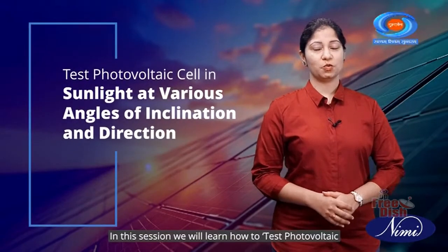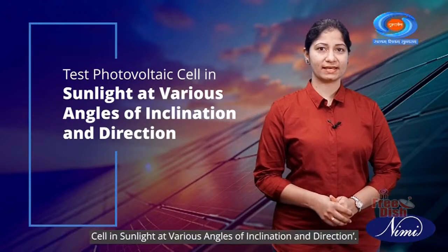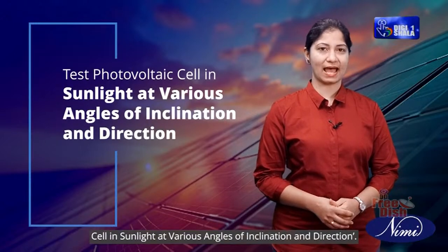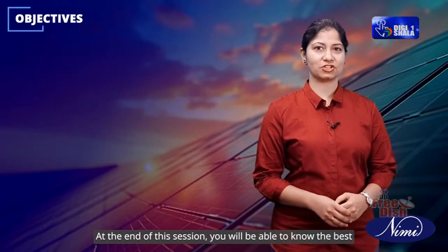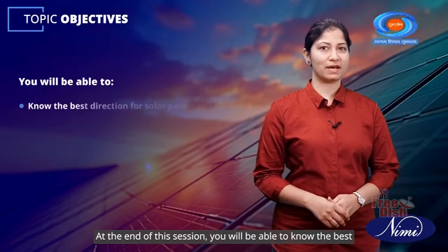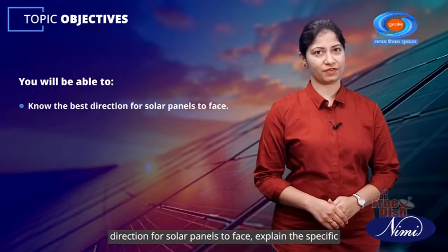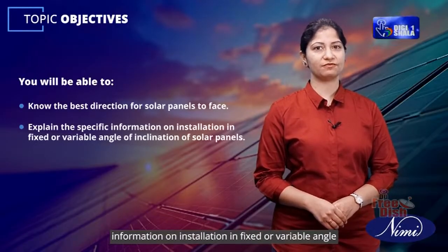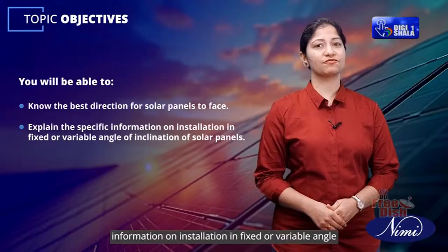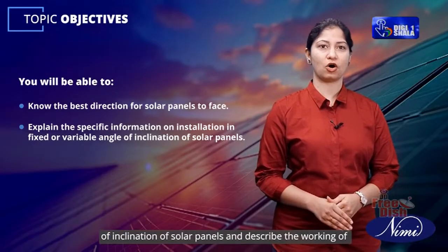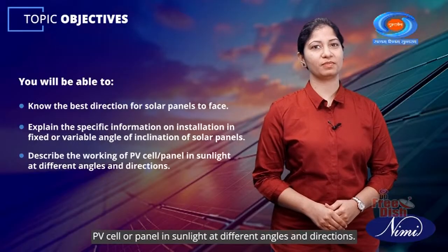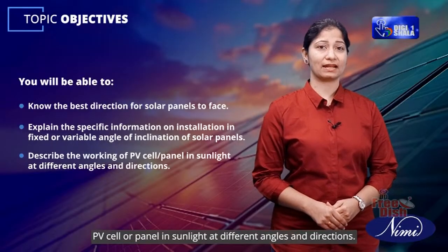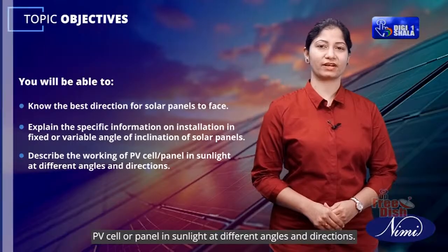In this session, we will learn how to test photovoltaic cell in sunlight at various angles of inclination and direction. At the end of this session, you will be able to know the best direction for solar panels to face, explain the specific information on installation in fixed or variable angle of inclination of solar panels, and describe the working of PV cell or panel in sunlight at different angles and directions.